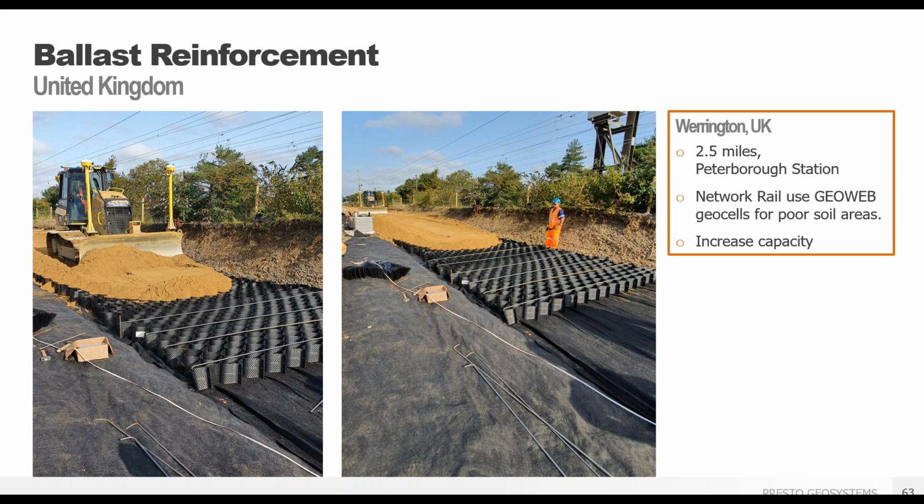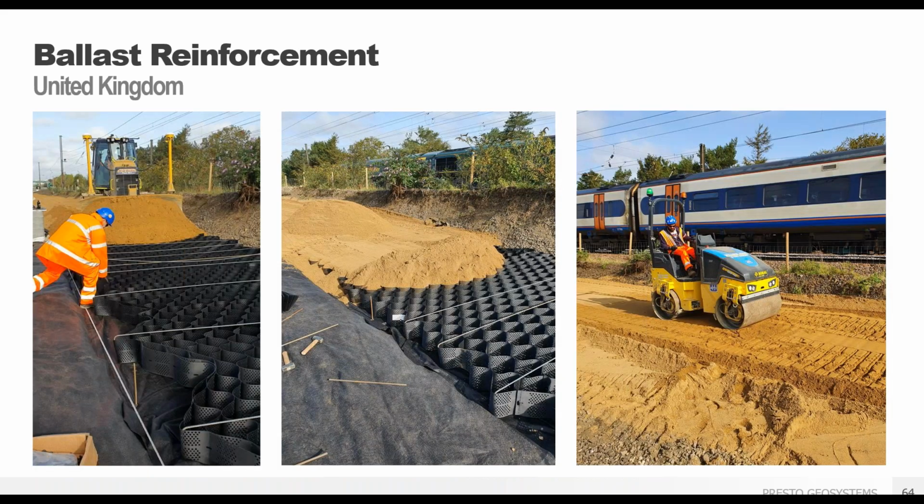You can see here's a low quality, locally available sand fill, so very, very inexpensive, filling the geo panels before the ballast went down. And as they're filling, you just remove those stretcher bars. Then compaction. Like I just mentioned, one thing about compaction.